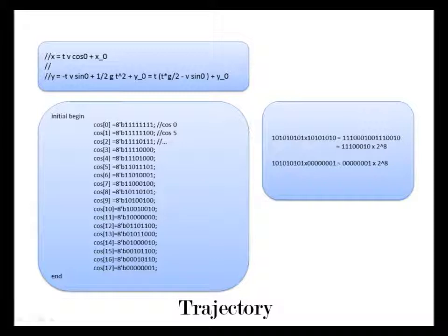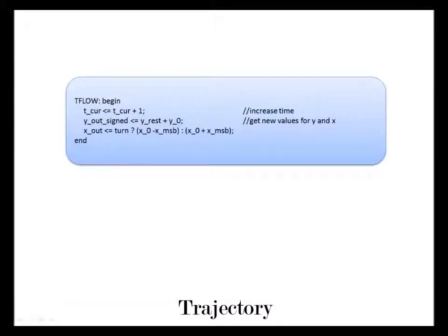In order to put a difference between sine of 0 and sine of 5 degrees, we represent our velocity by 9 bits, so that the sine of 5 can have an impact using the most significant bit of velocity. The calculation is done with combinational circuitry, but the values are correctly calculated because the state machine clock is slowed down. A slow clock is already required to slow down the ball movement on the screen.